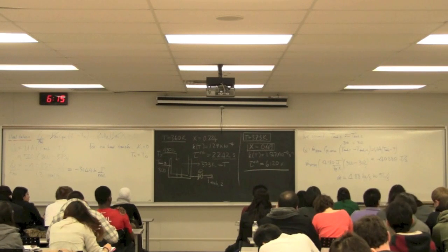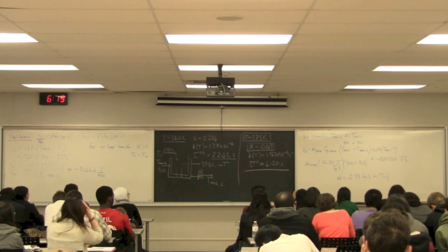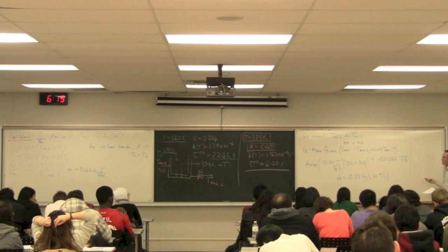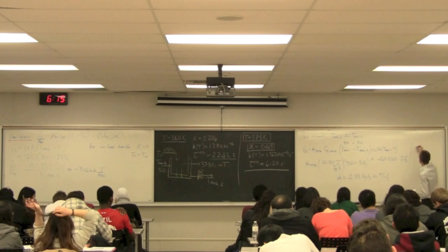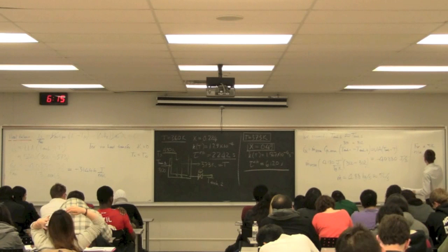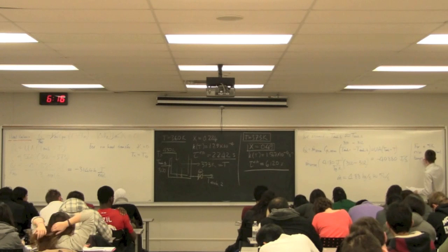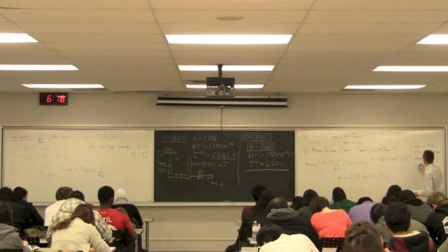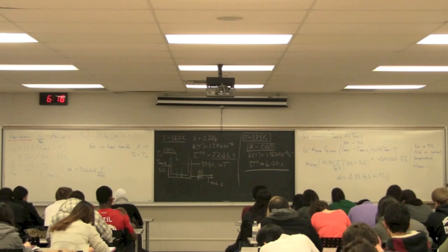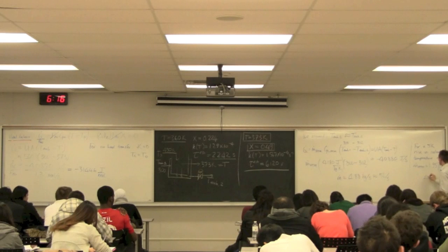If we only want a 2 Kelvin increase in my temperature leaving, I have to really pump water through there at quite a rate. So we can quickly trade off here. Well, let me accept a 5-degree rise. So for a 5 Kelvin rise in coolant temperature, we'll find that the mass flow of the heat transfer medium comes out to a more acceptable number in the order of 1.95 kilograms per second, or about 2 liters per second.